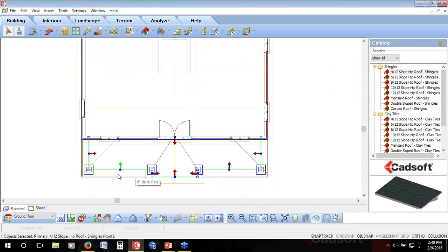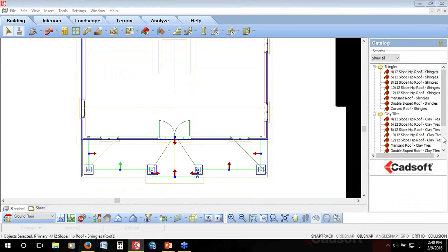But at the house, where I necessarily wouldn't have one because it's against the house, you would need some kind of drainage there, so you would make that your hip instead. I'm hoping that's what you're trying to create, and that's what he wants. But if it is, just think of the individual sides and think, is it a hip? Is it a gable? And a gable, remember, being anywhere you wouldn't hang a gutter or an eaves trough, and then use that kind of logic on each side to form it.